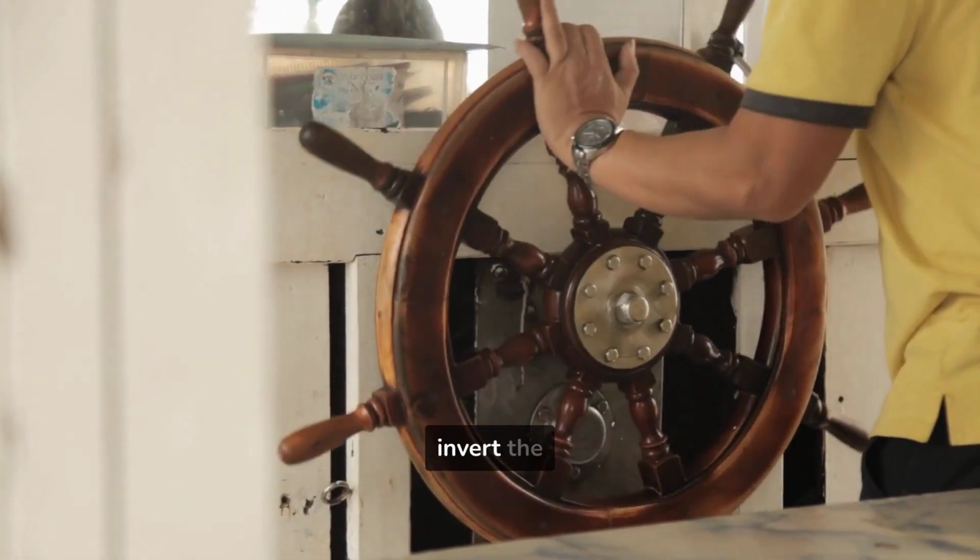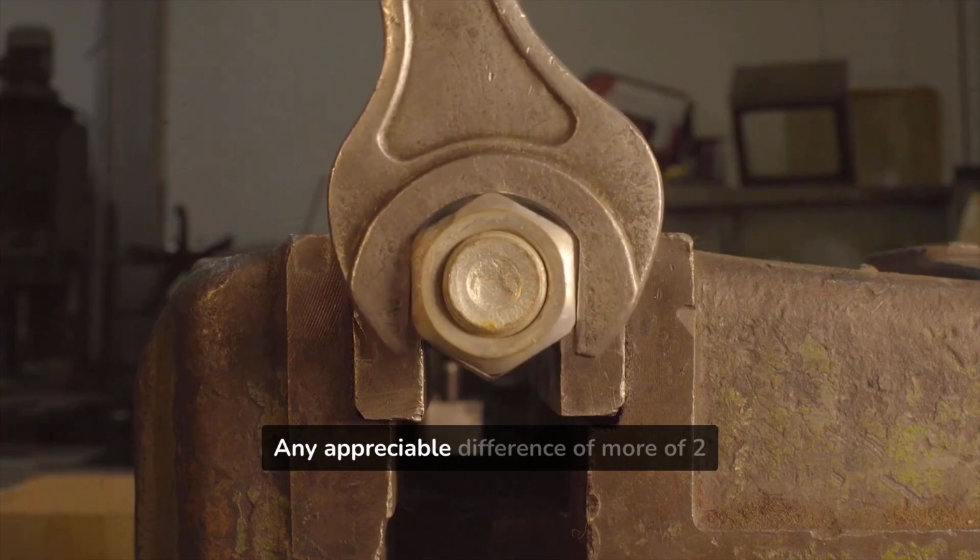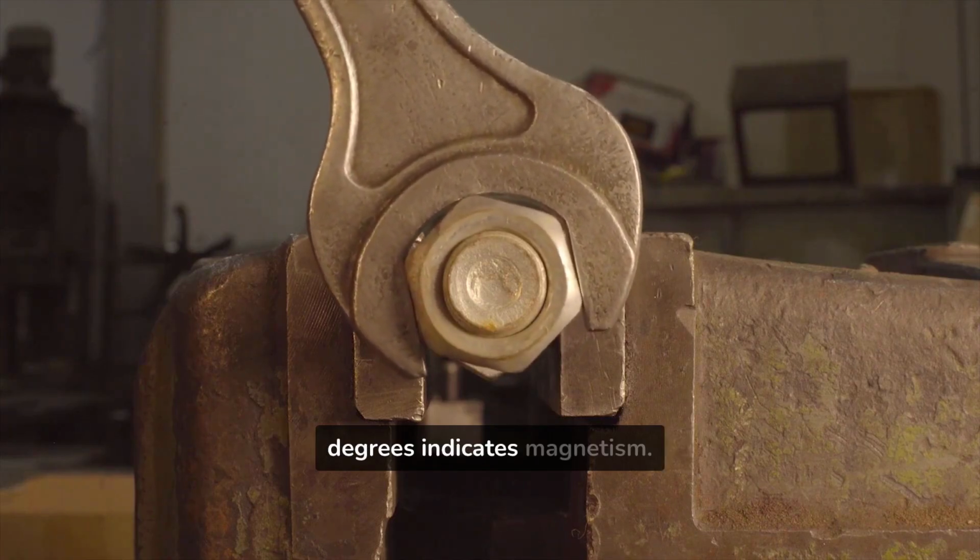With the Flinders bar it is rarer, but if in any doubt, note the compass heading with the Flinders bar in the holder, invert the Flinders bar, and again note the heading. Any appreciable difference of more than 2 degrees indicates magnetism.